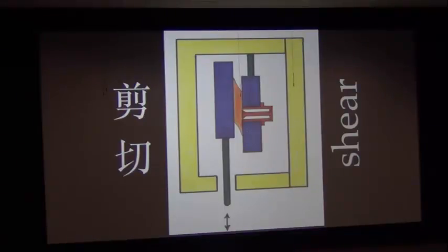But I think you can see that if I apply a large enough displacement to the plates, then these free boundary flows are going to get in the way, and you're not quite going to get the shear stress, which is why you might use a shear stress transducer, and we'll talk about both of that more later.